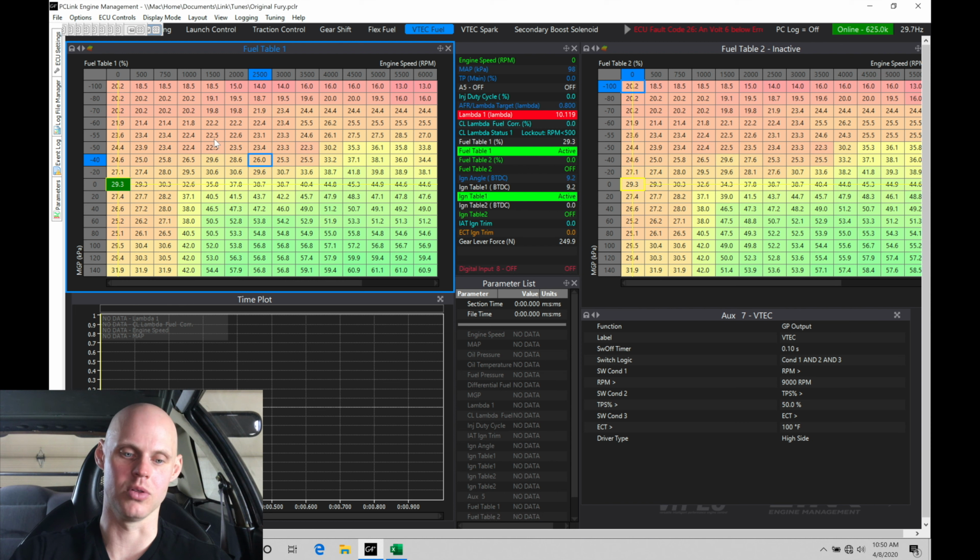Also, the values in the table that we're finding, these are going to be VE or model mode, volumetric efficiency based. These values aren't relevant. We need to put some reasonable values in here to get the engine fired off, because these values are way too low. So let's do our first thing. Let's change our tables up.